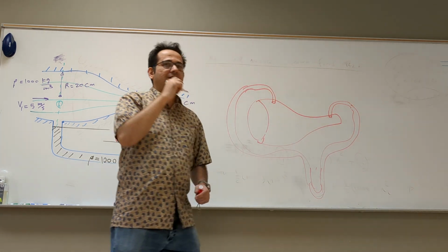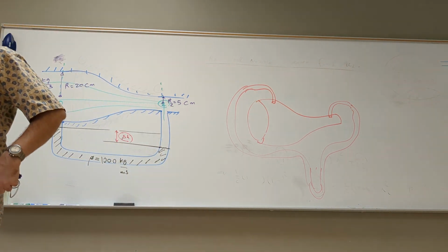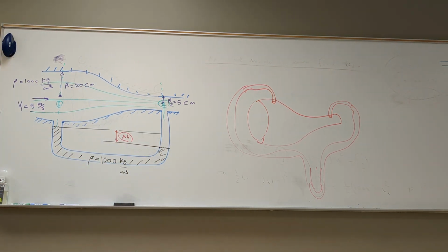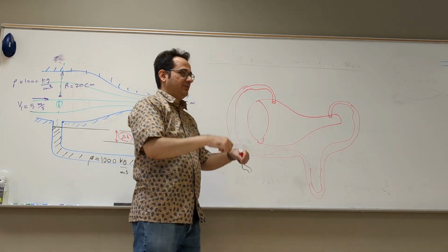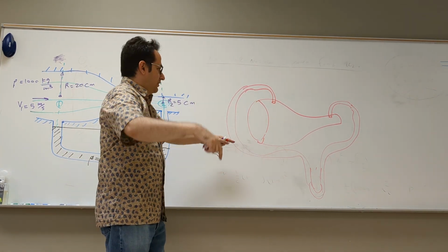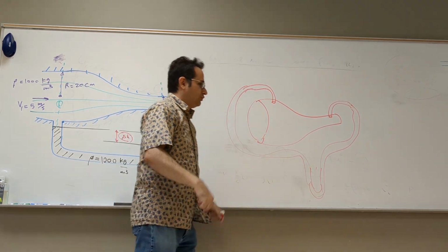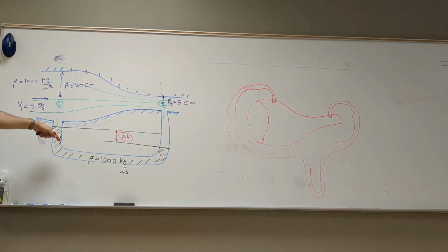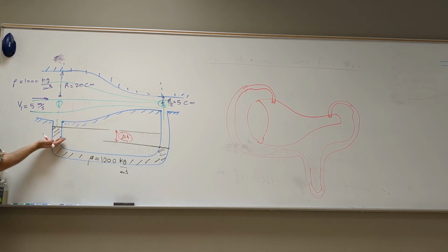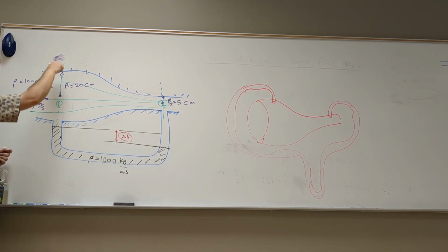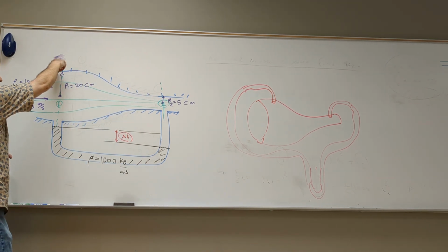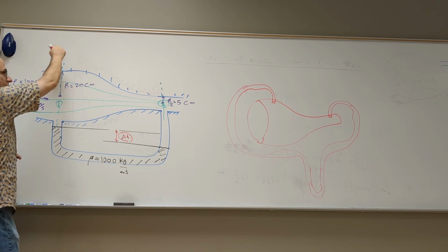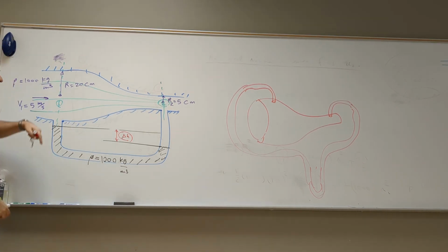If you did the static lab last week, you know there was a long tube that goes on top and not from the bottom, because it leaks. It was connected to two columns, and you could measure the pressure in height. So this point is not on the bottom, because it's going to be somewhere on top, and there is a valve, so there is no way the fluid can go from one to the other.